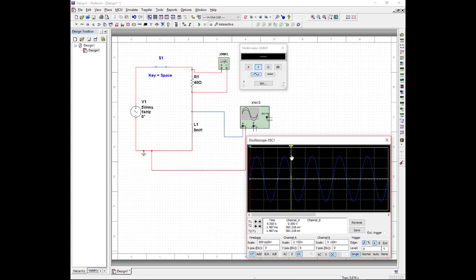Okay, so we'll use that to set up, we'll say a zero crossover here, and then we can move the other one to this zero crossover here, as close as we can. Okay, and now between the two cursors, so T1 is the first cursor. All right, I can see what time it's at, and I can see the voltage value that it's at. Okay, this is minus 55 millivolts. T2 is at 1.49 milliseconds, and it's 100 millivolts, thereabouts. Okay, and the bottom down here, T2 minus T1, gives us the difference between them. Okay, so it's giving me the relative difference between them.